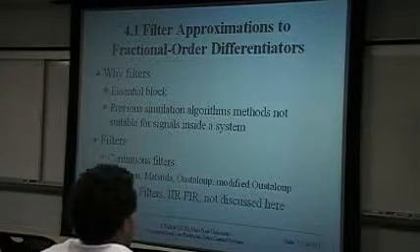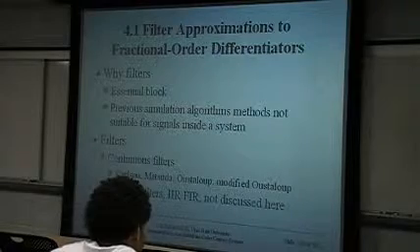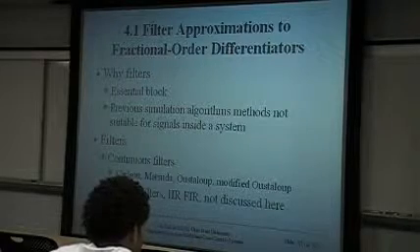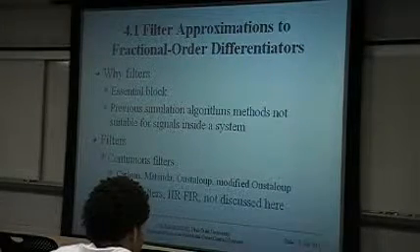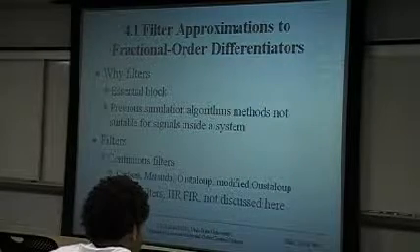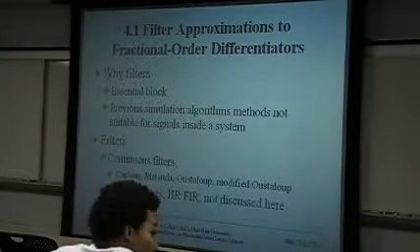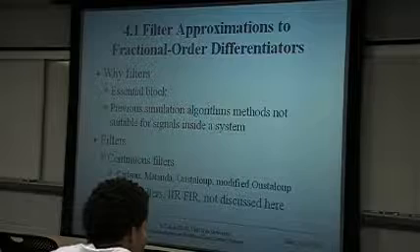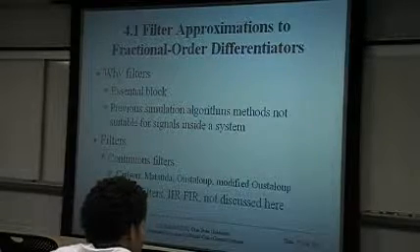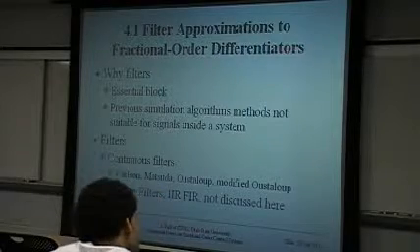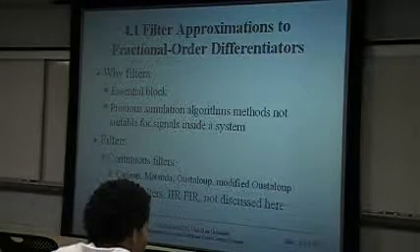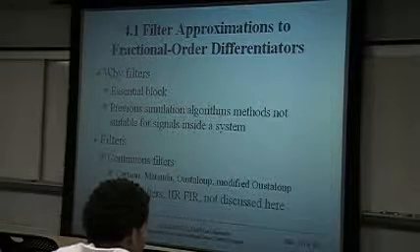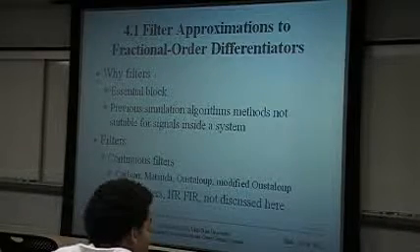And let's consider this one. And actually, I will demonstrate that one later to you. If you write it like this, this could be the differentiation equivalent to the transfer function. That should be okay then. So what you need to do is to introduce y equals u minus the derivative of y. And if we are trying to draw a block diagram, you have to define a y signal here.